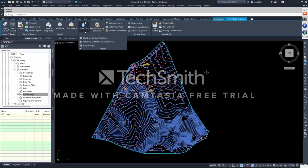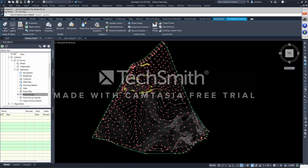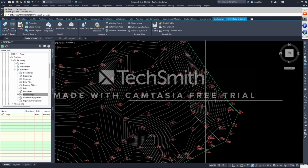I can do a water drop, which Civil3D civil guys like myself love, because that lets me take a water drop, literally a drop of rain, right? I hit water drop, set it up. I could tell it to do a 3D, put it on a specific path, tell it to have a marker to tell me where the starting of it was. Hit OK. Find a high spot. Turn off my OSnap. So that's 180, 178. I'm going to click right there. And it just traced, if I drop a rain hit here, where is it going?